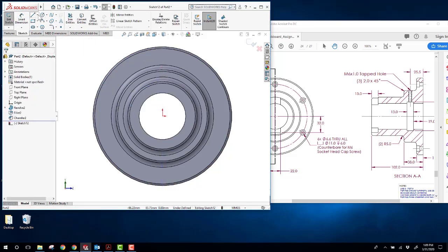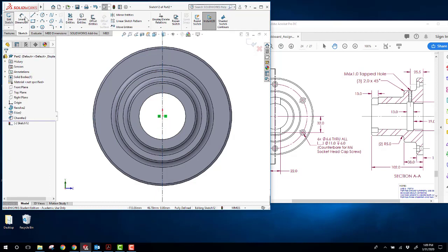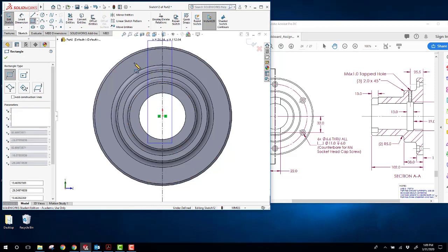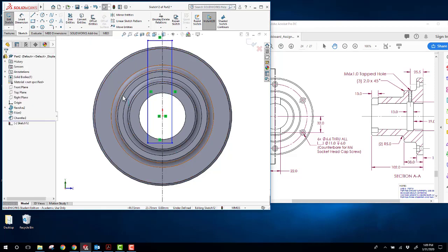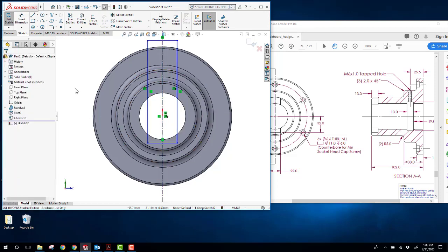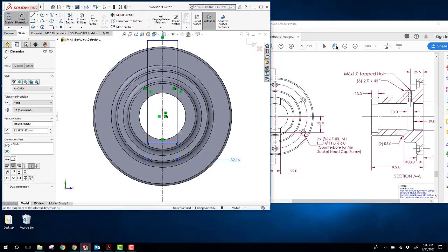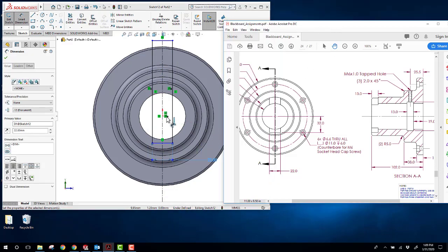All right, now I'll put a center line in. I can make it vertical and infinite length. So I'll do that. And then I'll just put a rectangle in to go from here, and the upper length doesn't really matter. I can do a symmetry constraint, I guess would be what I can do here. There's lots of different ways to make that where we want it to be. So it's 22 millimeters wide, and the distance from the center to the edge here is 32.